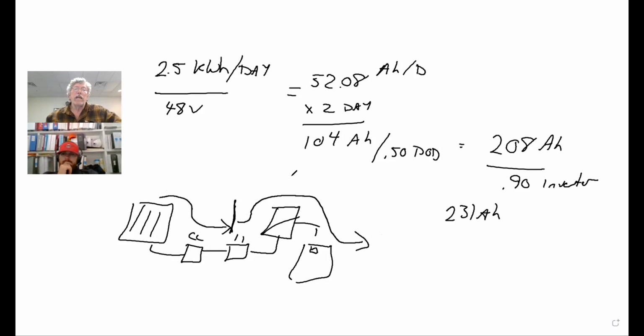So 100% of what goes through the inverter is based on the load. And the maximum power draw is the maximum load that can occur at any one time. So that's what's going to determine the size of your inverter. So that is what the case is in a standalone system.